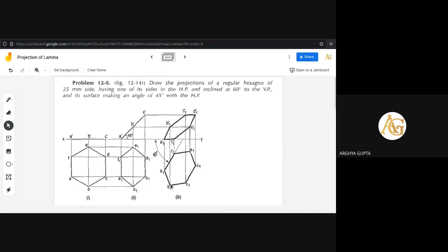Now B, through B, draw a vertical line, and those will intersect with B1 dash. Next, B and E is on the same line, same point, so draw a horizontal line, and through E, draw a vertical line, so E1 dash will be found. Now D1, draw a perpendicular line, CD is the same point, so draw a horizontal line, so D1 is found.